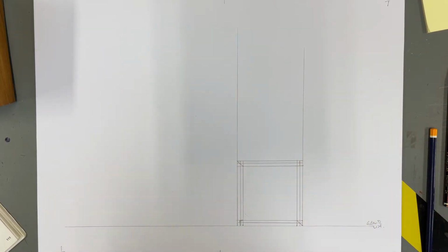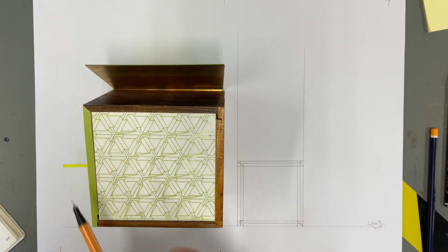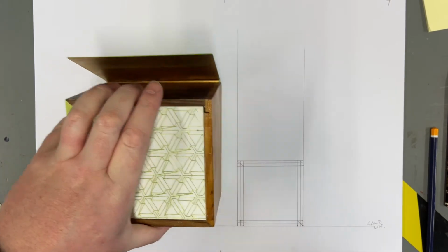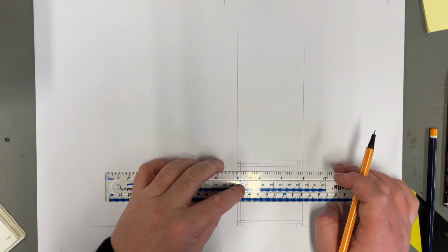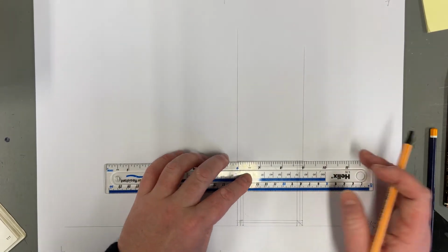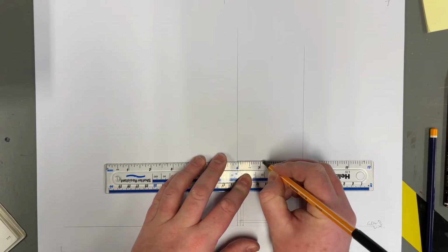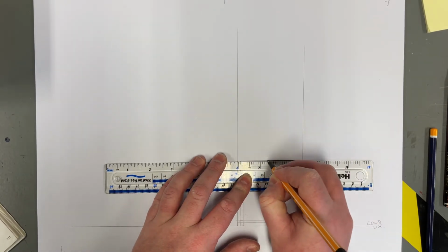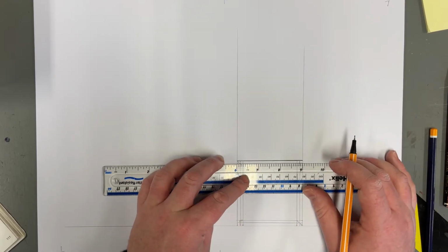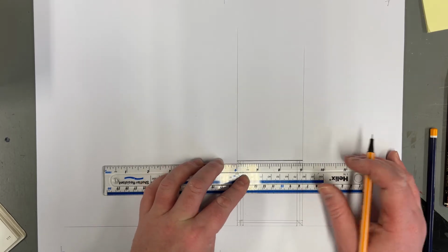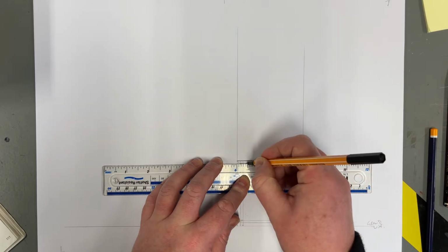Now, in terms of lining in, we have to line in what is clearly visible to us, what we have direct line of sight to. So on the sketch, I'll start with all of the horizontals first. So we would see the top edge here. Okay, now I'm doing this in pen. You are welcome to do it in pen if you feel confident enough. If not, just a little bit heavier with your pencil.